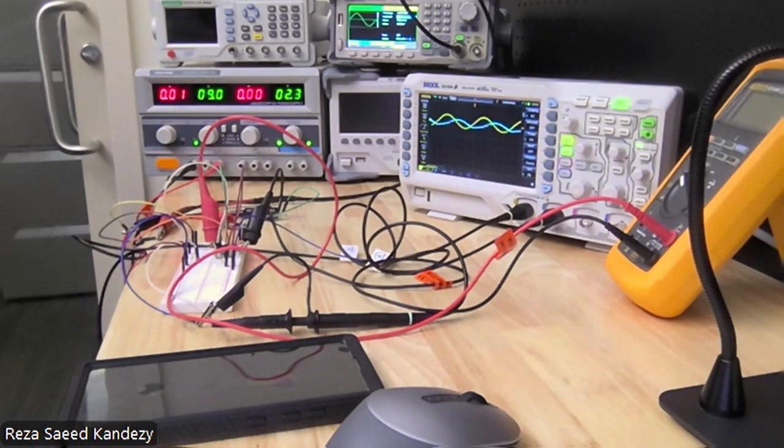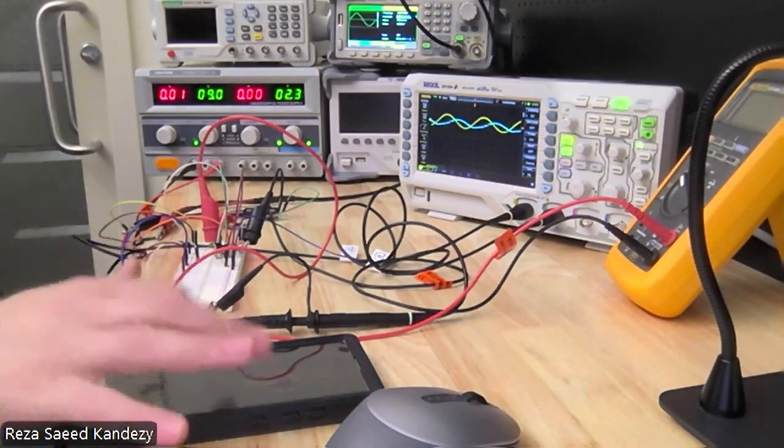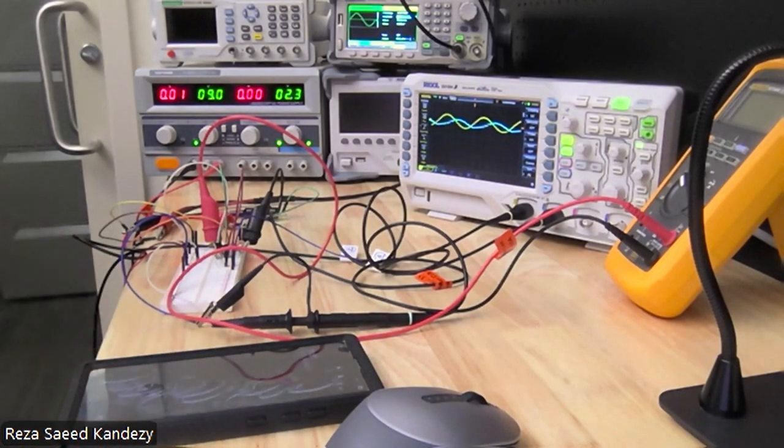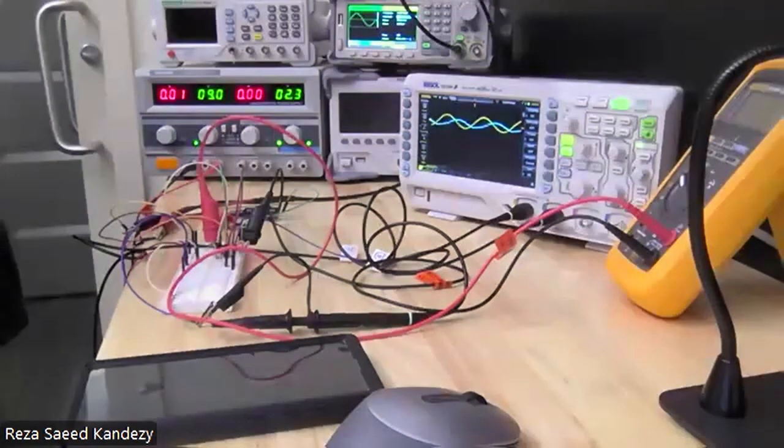We saw that based on those values, my theoretical gain should be 3.63. What I actually have is 3.33, which is very close, and that difference is, as you know, because of the errors in the resistance. But the main source is that we considered our beta equal to 100, which we know is not going to be exactly 100.